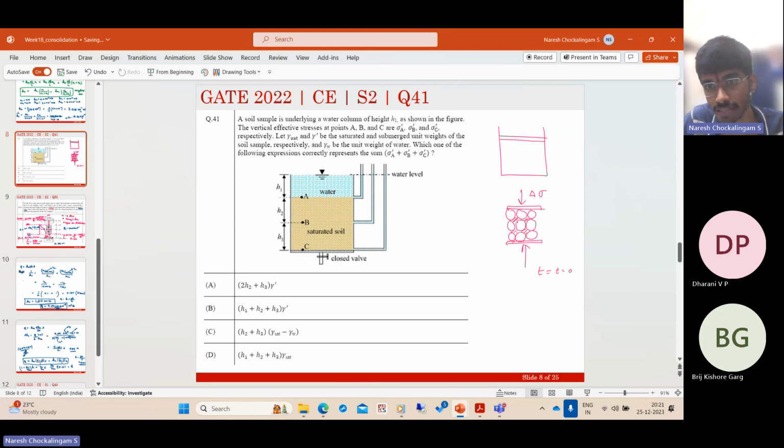They'll try to pack close to each other. In that process, they will pressurize the pore water pressure. But as you allow drainage, when you allow the pore water to leave, water is usually incompressible. Water is treated as incompressible in saturated soil mechanics. So instantaneously, the particles will try to come close to each other, but they cannot because the pore water is there. Pore water will take up all the pressure. It is incompressible. It will take up all the pressure and resist the applied force.